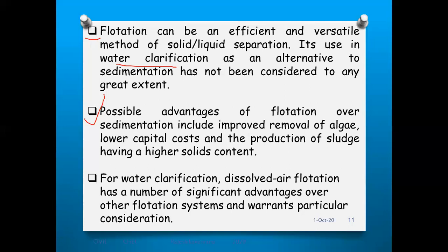For example, if the sedimentation process is taking 60% of sludge in the tank, whereas this flotation process is taking more than 75% or 80% of solid sludge in the tank. So these are the possible advantages over the sedimentation process.